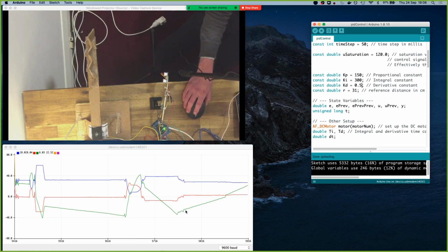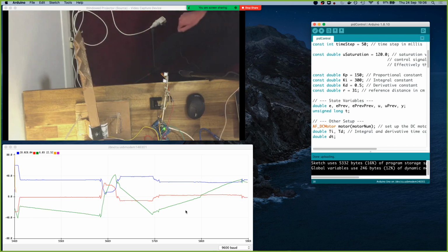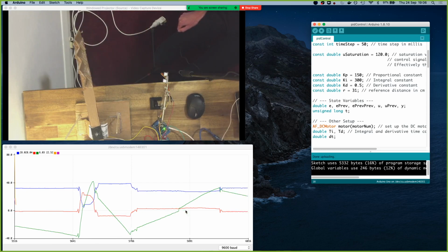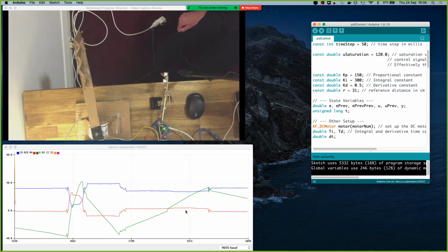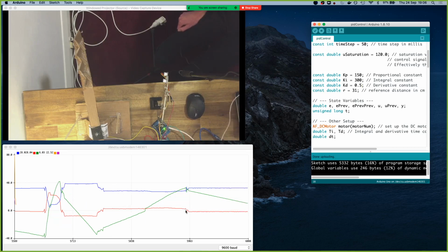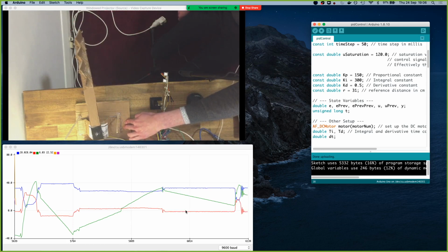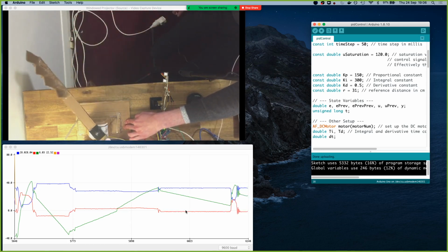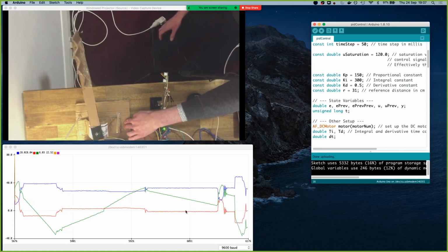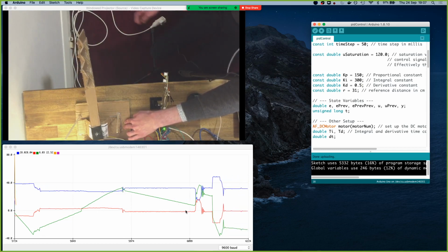Typically you'll find there's something called a dead band. We get to that equilibrium basically, and even though there's a little bit of noise, the difference in value might be like 2 or 3 centimeters, but that may be good enough for us. So you say, if my error is below these bounds, we don't need to do anything. That's called a dead band, which I haven't implemented here. But yeah, this is quite nice. It just takes a while to shoot back in the other direction, doesn't it? See, that recovered in basically one oscillation, an overshoot.